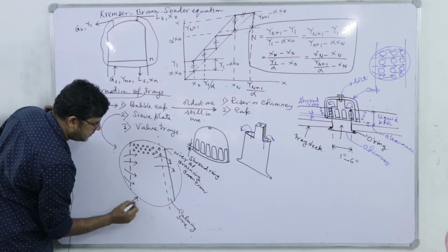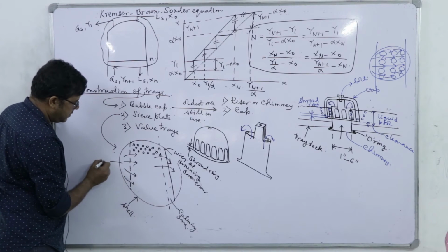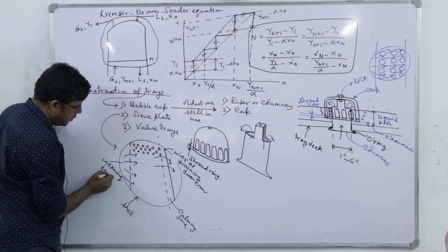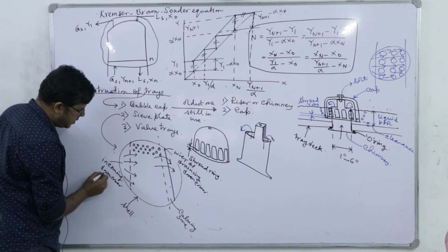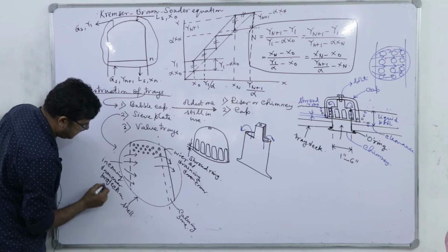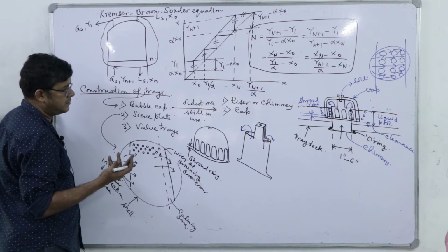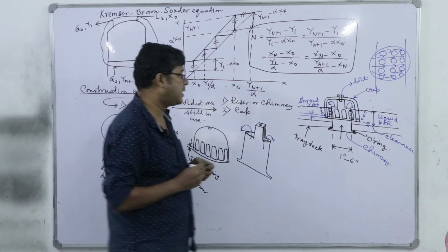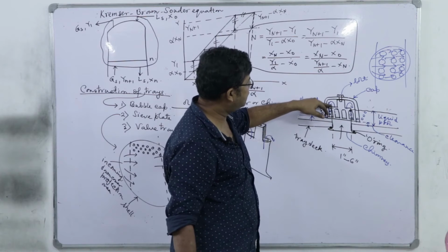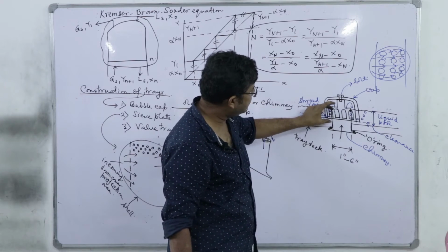This is the shell, right, and the incoming downcomer area, a downcomer projection area and all. Now these sieves, you see, it's simply open, right? Here in the bubble cap, if the liquid has to percolate through the chimney, it has to move above and over this height, okay?